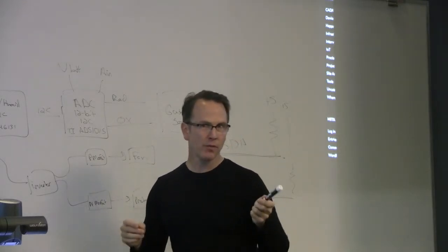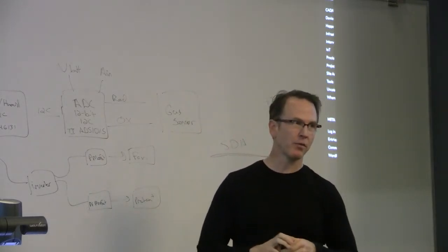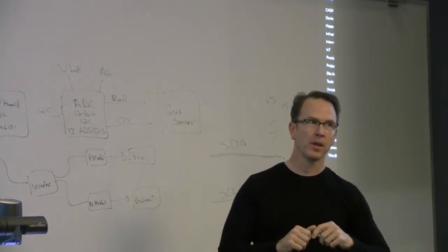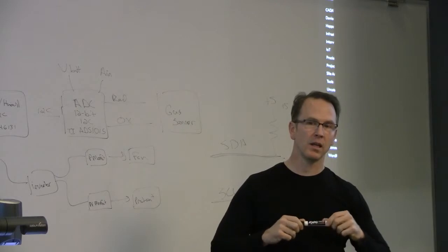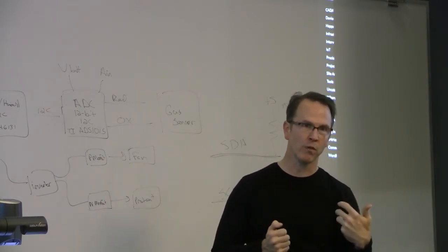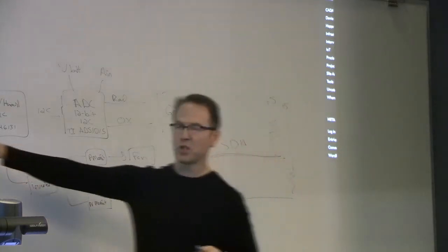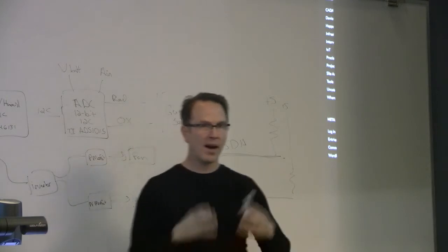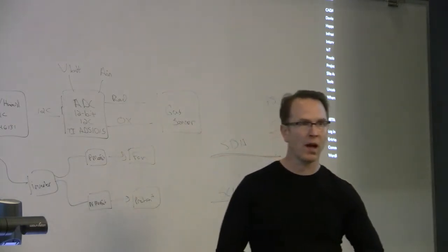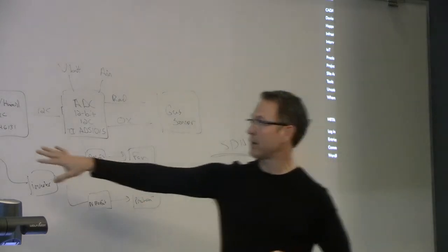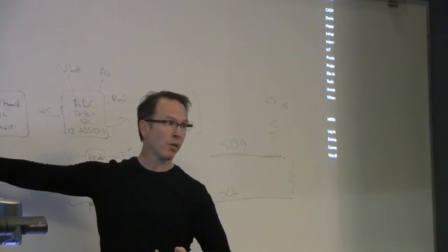The only thing with the level shifters, like I had a level shifter from SparkFun or something, is the bidirectional nature of it. You have to shift one way and then you also have to shift back. And this chip is cheaper than buying however many of those level shifters you need, I think. It's just like $1, maybe $1.20, $1.30.